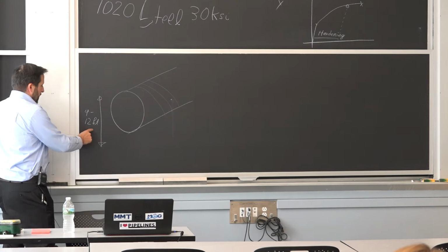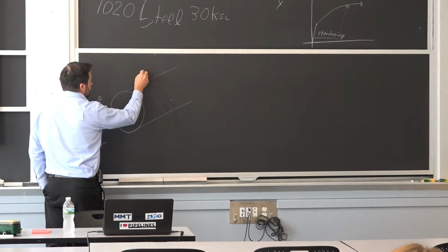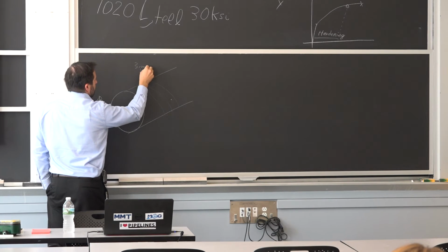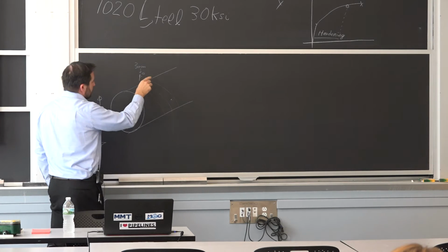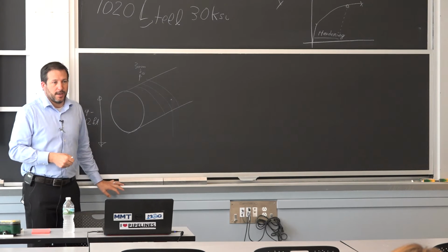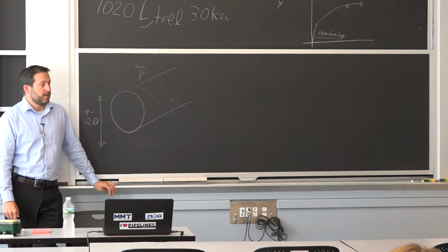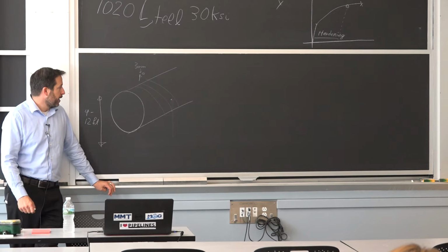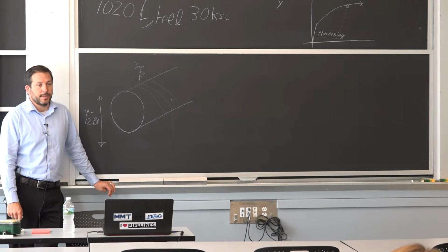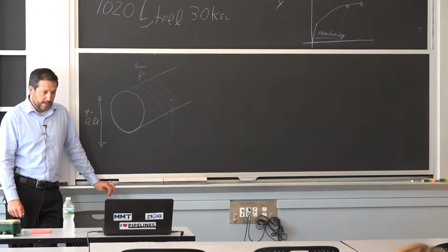Because we're looking at a very large diameter, and these wires would be very tiny, let's say I'm talking about a 3 millimeter wire, it doesn't really get any kink when you're forming it. And that's the low-cost solution to be able to carry water at hundreds of PSI of pressure across Africa or here between the cities for supply.